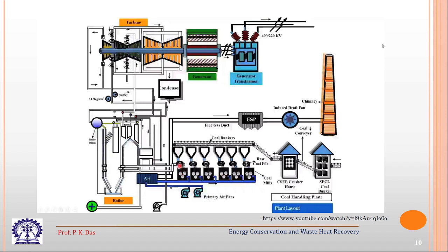Along with air, it will be injected into the boiler, and some extra air will also come. We will see when the animation runs. Here this is the furnace portion of the boiler. Here we will find the flame etc., and at the side we have got the tubes. And this is the steam drum, boiler drum or steam drum. In the boiler drum we will have generation of saturated steam. The wall of the boiler will be utilized for generating the saturated steam.